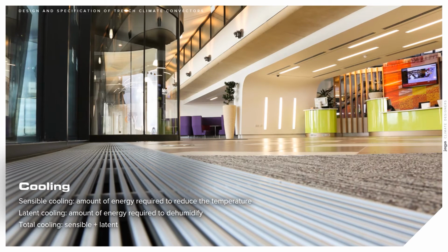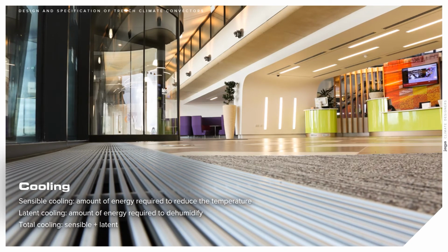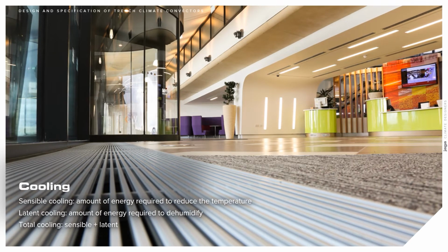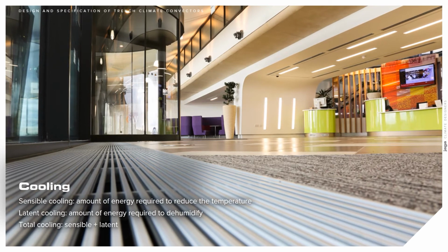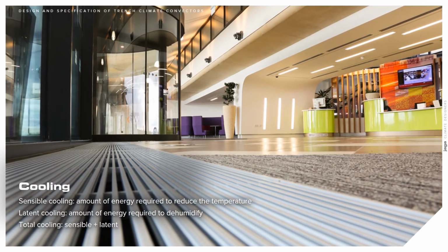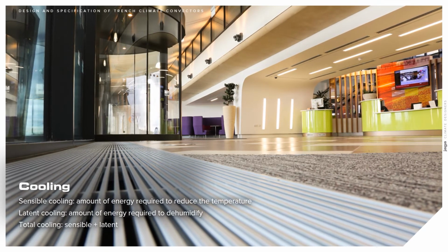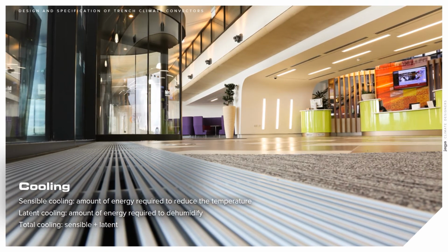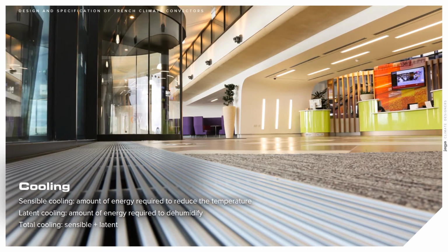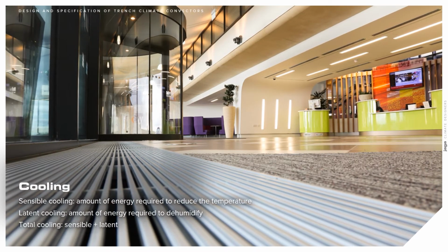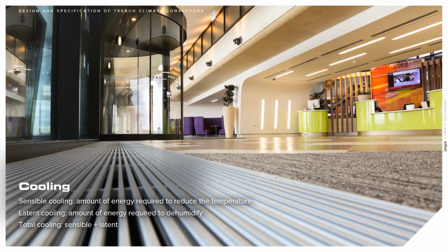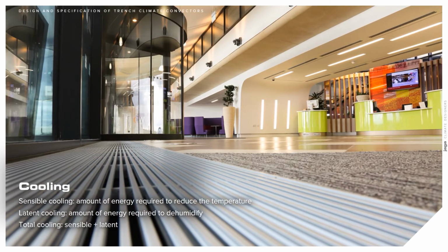Latent cooling load is a measure of the amount of energy that is necessary to dehumidify the air in a building. Dehumidifying is effectively taking the moisture out of the air. It's normally the humidity that is more uncomfortable for occupants than temperature. Total cooling is sensible plus latent. It's the total calculation that should be used when selecting trench climate convectors for cooling.